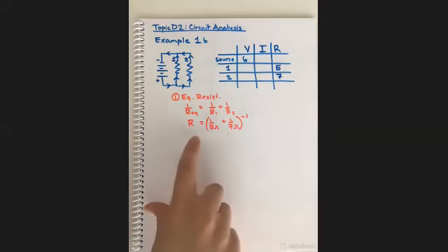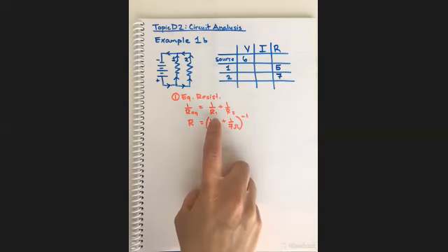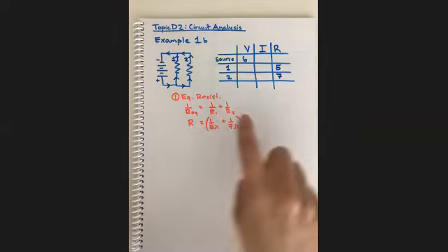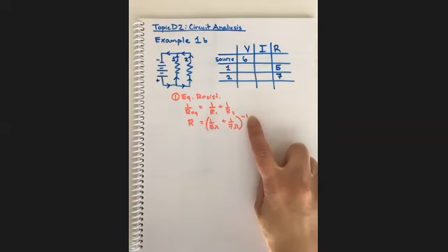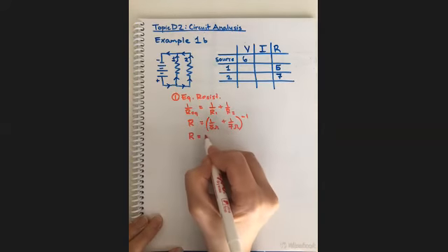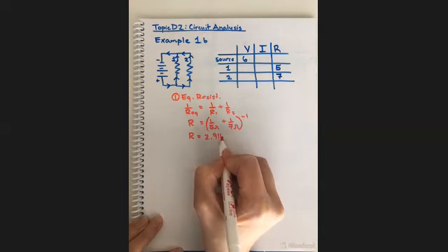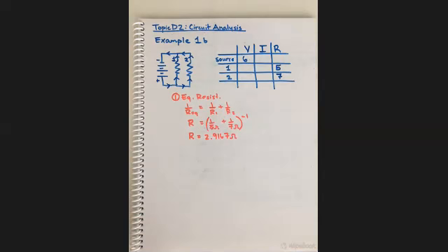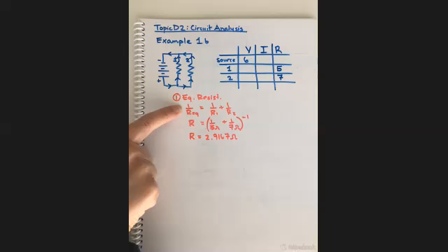Okay, we're back. So for resistance, on our calculator we do 1 divided by 5 plus 1 divided by 7, and then we press the reciprocal button or do to the power of -1. So for the equivalent resistance, I get 2.9167 ohms. Now I do not get 0.3 something. If you got 0.34, what you solved for in your calculator was 1 over resistance. Remember to take the reciprocal because the equation is 1 over.